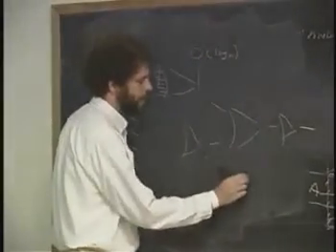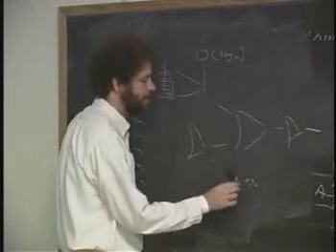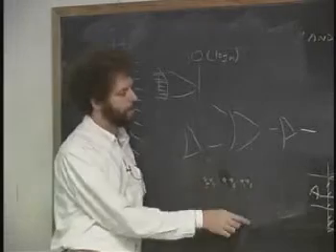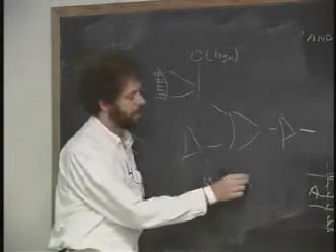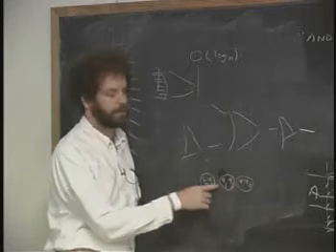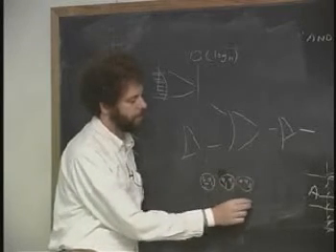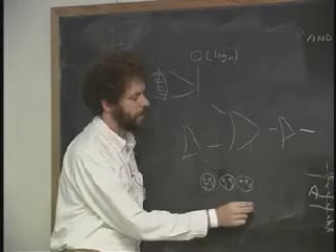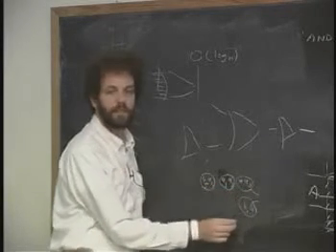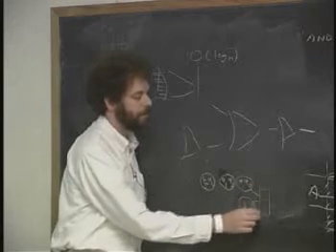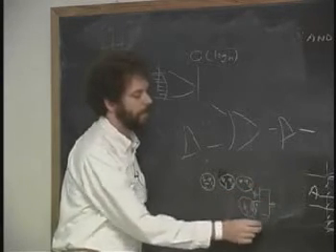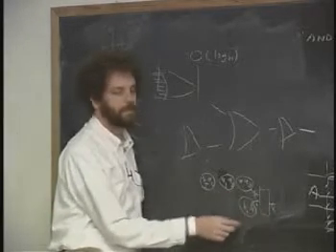So here's a sub 0, a sub 1, a sub 2, a sub 3, a sub 4, a sub 5. Rather than treating each one of these bits the way we've been doing now, treat them as little groups. So here's a number between 0 and 3, here's a number between 0 and 3. And instead of adding bit by bit, we're going to add a number between 0 and 3 to another number between 0 and 3. Worst case, we'll put it into a lookup table. There's 2 bits here, there's 2 bits here. We can do this pretty fast, and we can get two bits out that's a little bit faster.